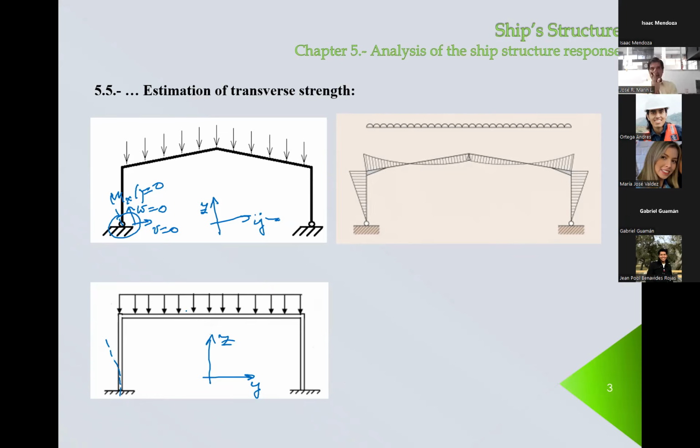So you start vertically, and then you can deflect to one side or the other. But here, there is no rotation. In order to avoid having rotation, you generate a bending moment here. So yeah, you're right. That's going to be the larger difference with the other case.